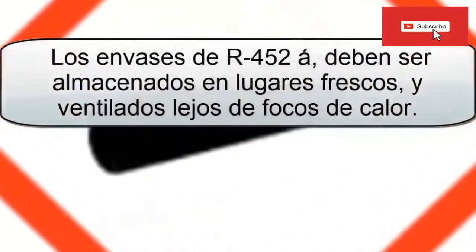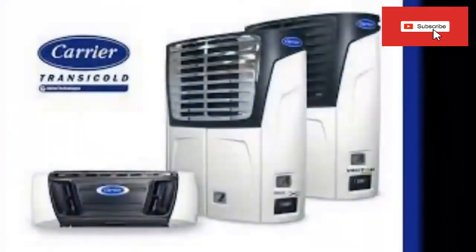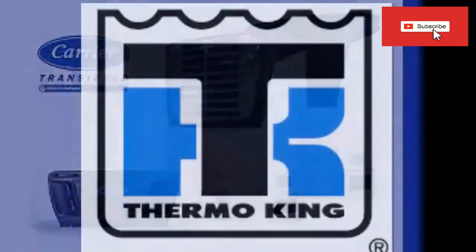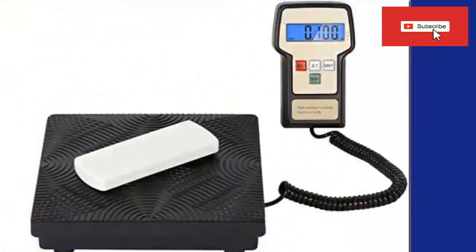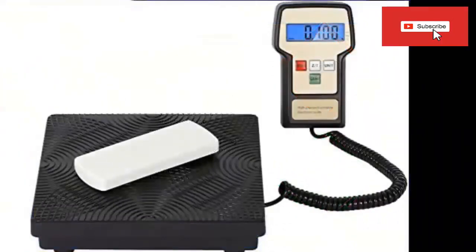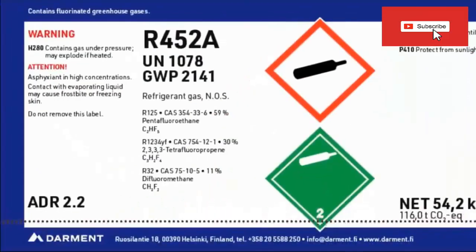18. R452A containers must be stored in cool and ventilated places away from sources of heat. 19. Two of the main manufacturers of transport refrigeration equipment, such as Carrier and Thermo King, offer equipment with R452A as an alternative to R404A. 20. The use of a scale is recommended when loading R452A. Also, if possible, it should be loaded in the receiving tank, or in the liquid line.